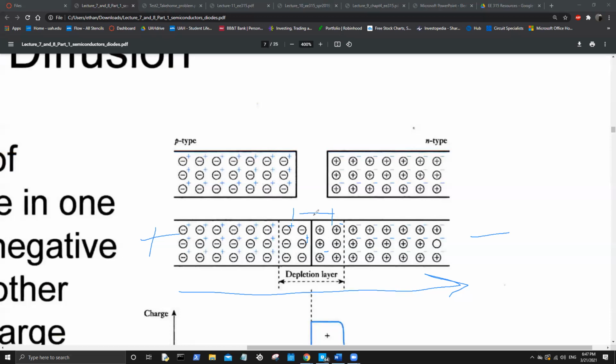Now the depletion layer, I don't think ever drops to 0. I think it's always there, but the resistance of that intrinsic silicon drops to a point where it's fundamentally not there and you don't need to care anymore. That's the same reason this junction still dissipates energy in the form of heat, because of this resistance, which is disgustingly higher than this or this. Doped silicon's really good. So it's just about introducing those charges back to the system to take it from this fundamentally intrinsic representation and put it back to its extrinsic doped variety to allow charge to flow. And that's all due to the external biasing.